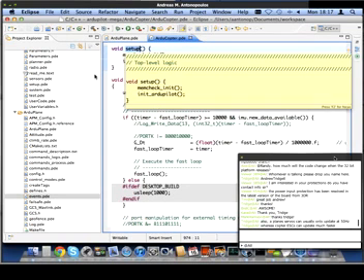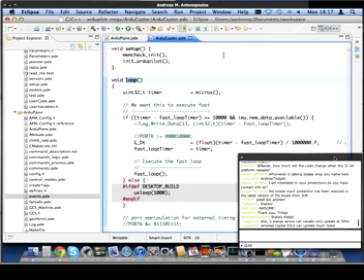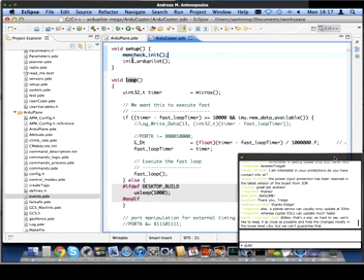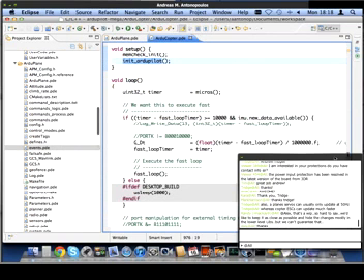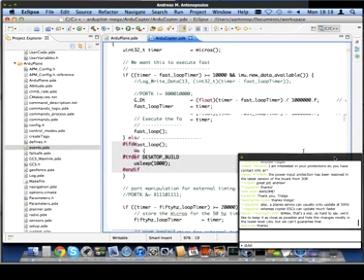Let me just get down there. All right, so this is the main loop in ArduCopter. As you can see, the two special functions, setup and loop, that are part of the Arduino code are here too. Again, very similar structure with the memcheck and the initialization function. Just like in ArduPlane, init ArduPilot will go and initialize all of the hardware, and that can be found in system.pde. So as you can see, the structure of the code is very, very similar.